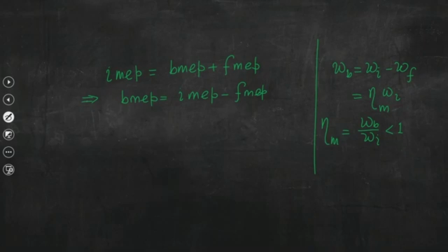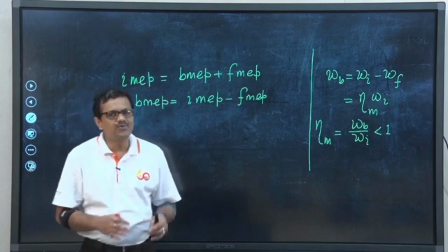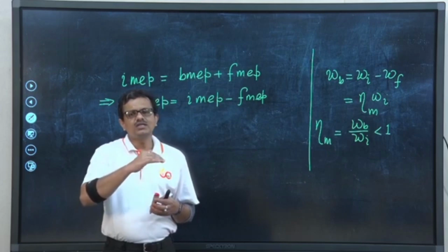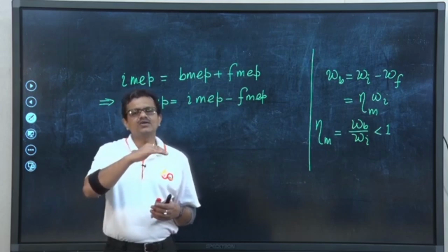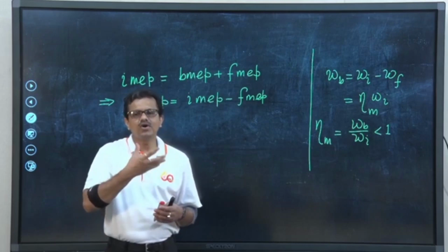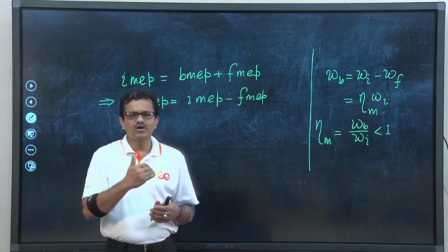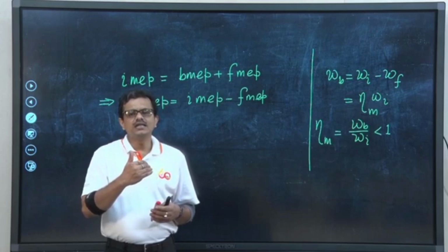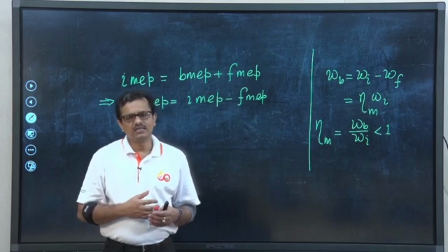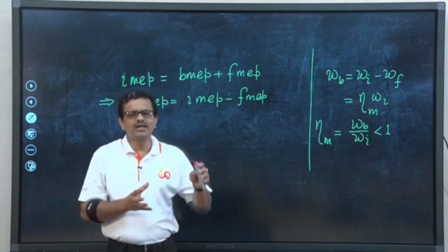We had also discussed the indicator diagram in the last class. If we try to recall the indicator diagram, about the atmospheric pressure line there are two different loops. The upper loop gives us the positive work, and that is the work we are getting, while the lower loop is the negative work, that is the work that we need to supply to the engine cylinder. So, the net work that we get is positive minus negative.